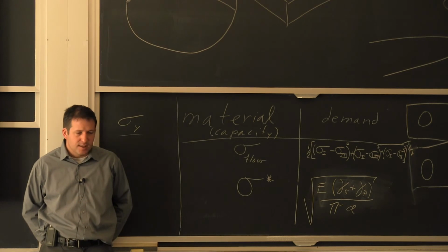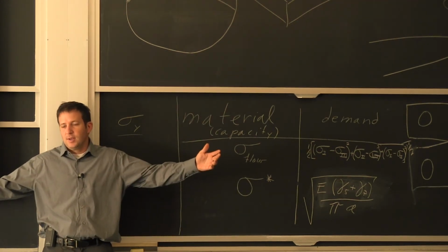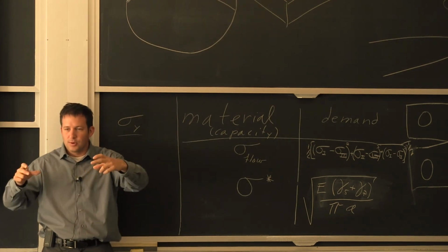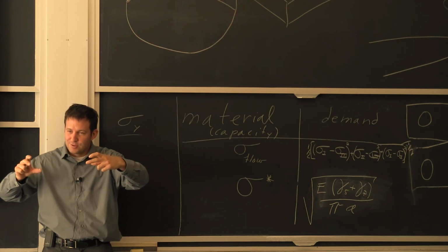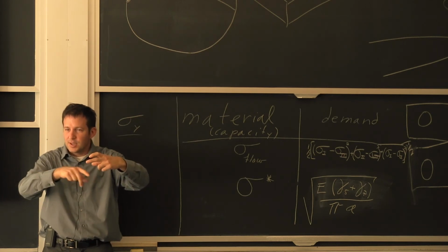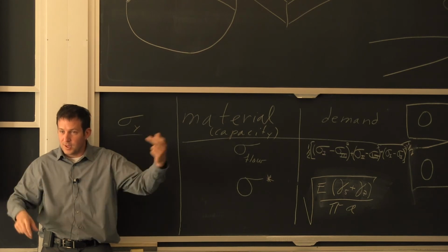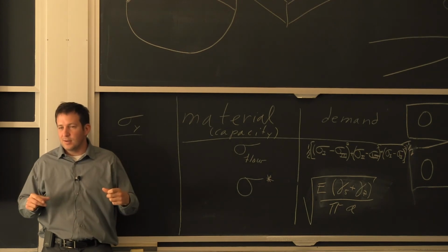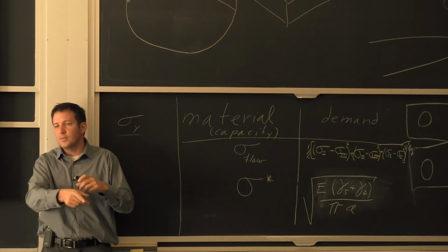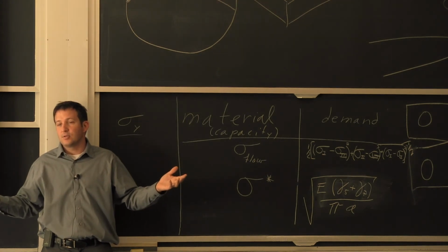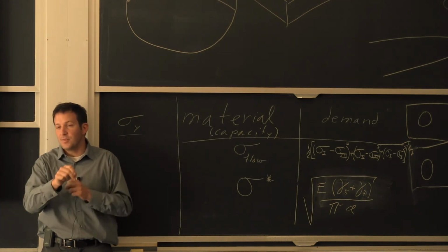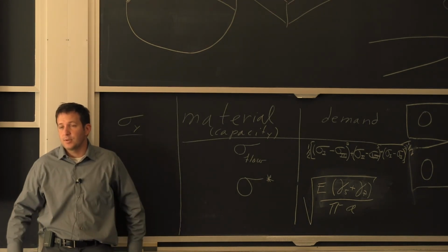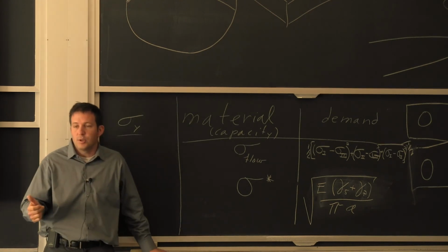You're also more sensitive. If you're looking at a whole assembly, a car is a good example. If I hit a bump on one corner of a car, a lot of times you have a little stretch, a little twist. It means in some of the connections, some of the welds, it will deform. You have plasticity. Well, if it turns out you made it out of a brittle steel, it's going to start to crack right there, even though overall you're not applying high loads, but you're just very sensitive. You're not forgiven for one or two overloads if you lose the ductility of your material. And that's the highest risk with embrittlement and cleavage.